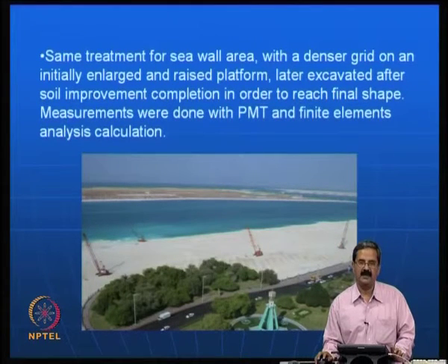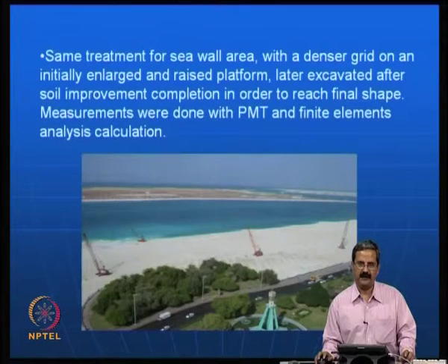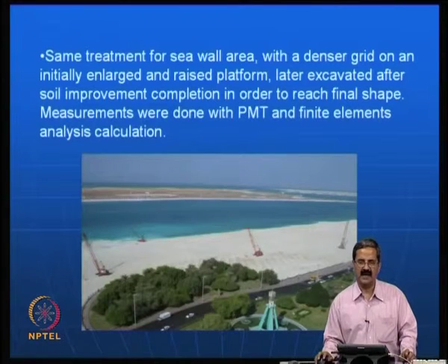And there have been many case studies even in India, where particularly in many of the coastal areas dynamic compaction was done. In fly ash ponds it was done. So it has been quite effective because the method itself is quite simple, like it only involves the weight to be dropped, and everything is pre-designed, say for example the height and the spacing.